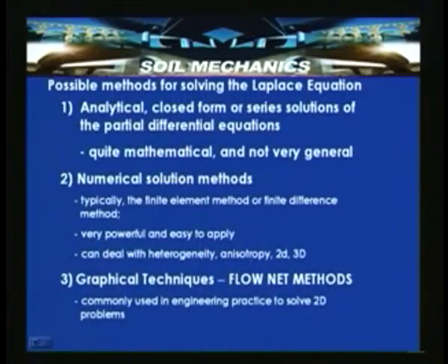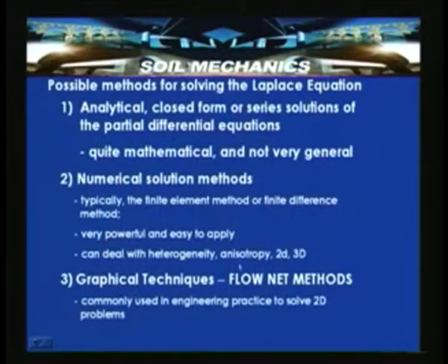basically there are analytical and closed form series solutions of the partial differential equations. There are several solutions available, and these analytical and closed form solutions are quite mathematical, not very general in nature. And numerical solution methods, typically finite element or finite difference methods, do exist and are very powerful and easy to apply, and can deal with heterogeneity, anisotropicity and two dimensional and three dimensional flow conditions.